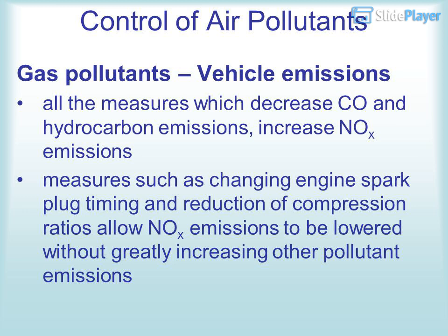Control of air pollutants. Gas pollutants, vehicle emissions. All the measures which decrease CO and hydrocarbon emissions increase NOx emissions. Measures such as changing engine spark plug timing and reduction of compression ratios allow NOx emissions to be lowered without greatly increasing other pollutant emissions.